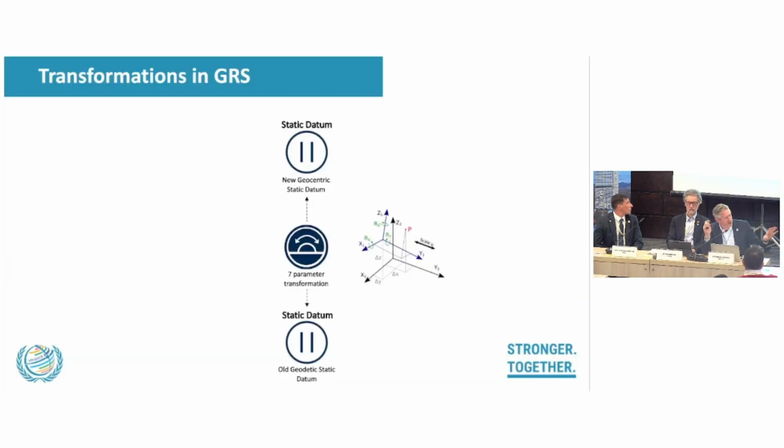So part of what we're going to talk about this week, following on from what you just said, is a great example of where it may be even more complex than this, but you've done the mapping to go from what you would get from ITRF to transform back to a static datum that users have. That can be done using a 7-parameter transformation, and we'll explain what that is later on. Or sometimes you need a more complicated deformation model or a distortion model.